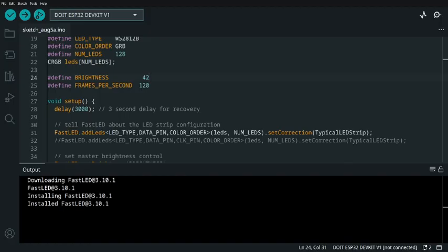Okay, hold on. Which one is the one that goes into the board? Well, all of them. Into the actual board. Which set of cords goes into this board itself? This one. So I need to remember which pins to hook up which ones to. So the red should go to 5 volt. The yellow should go to ground, and the black should go to data, I believe, because they don't match up the way they're supposed to. Like they don't match a conventional electronics color scheme. So red should be 5 volt.